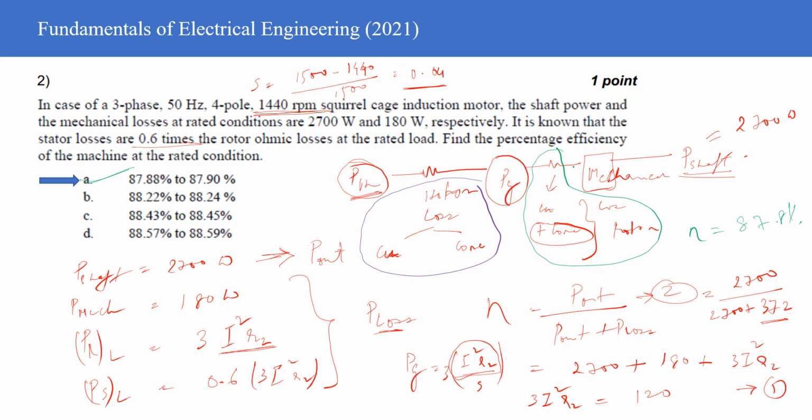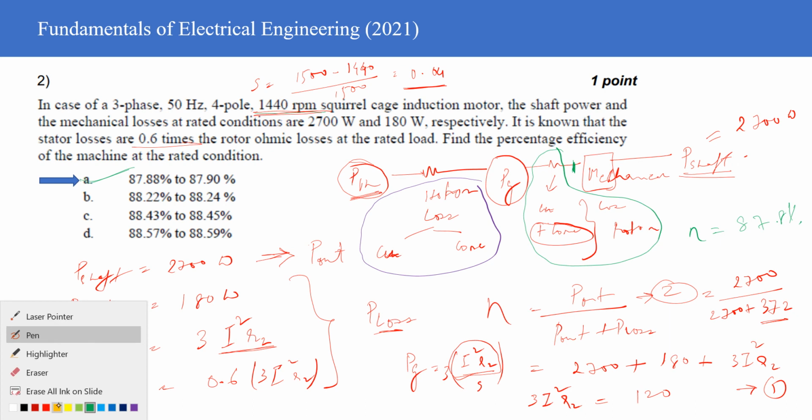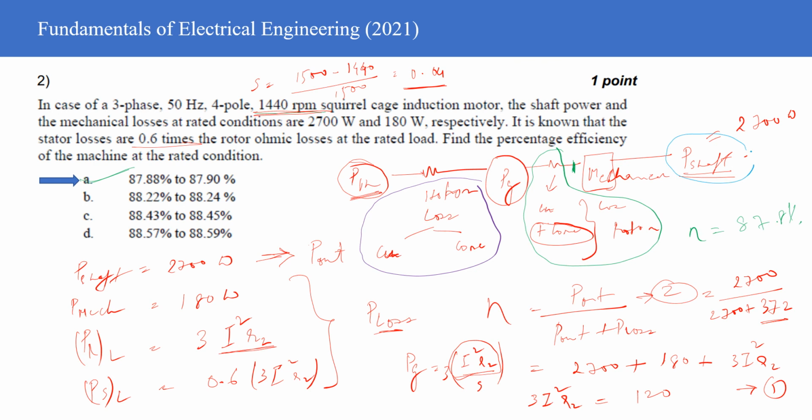So from this end, if you subtract the mechanical power losses, there would be some losses in the bearing of the machine and so on. If you subtract the bearing losses, mechanical loss, you will end up with the shaft power, right? So shaft power is nothing but the actual power which you are getting out of the induction machine, which can be used for driving any application, right? So this is the useful power which you are getting out of the system. So you gave in the electrical power here, and you got some useful power here. Everything in between is non-useful power, which is kind of losses.